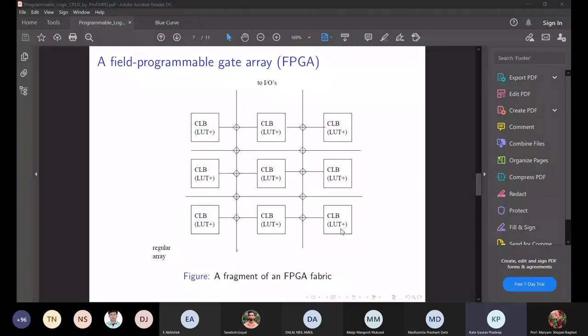Yeah, costly. Yeah, that's a correct one. Limited block RAMs. Okay, but let's say as compared to CPLD, what might be the limitations? LUT will have to store some not so useful combinations. Okay, but FPGA has a large number of LUTs, so I don't really worry about it.